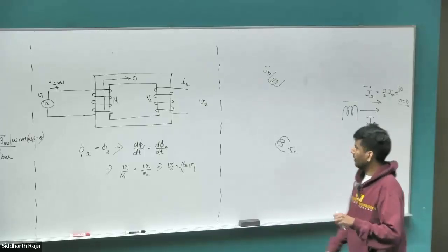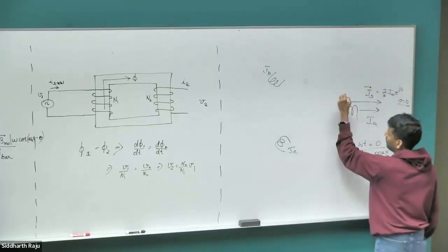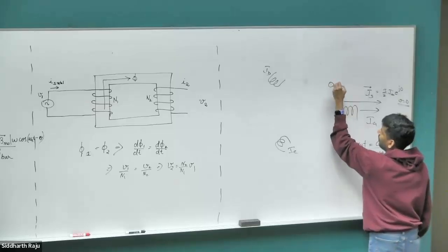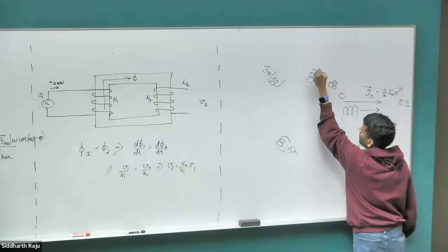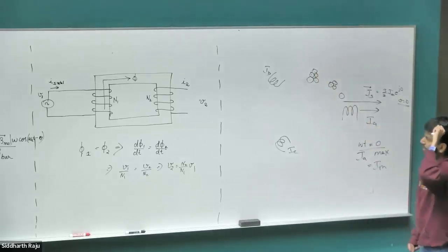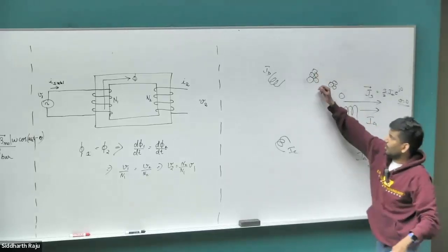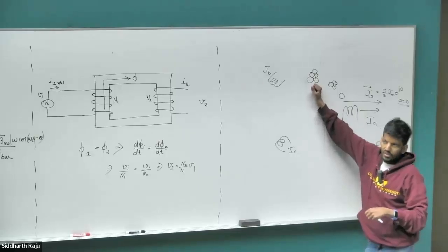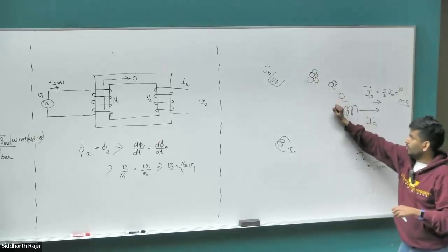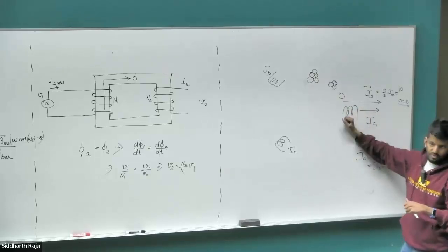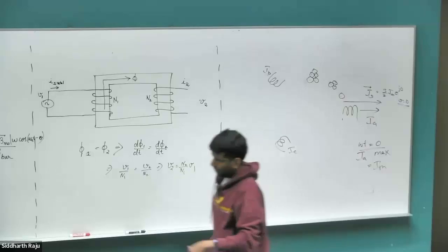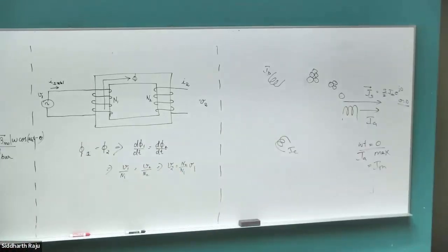90 degrees? 90 degrees. So when we have our conductor distribution, if you remember, we had one coil here, 3 coils here, and the maximum number of coils was at this point. So the Ni product is actually maxima here. And the Ni product is gradually reducing, with the lowest value being along where the magnetic axis of the coil is actually present. So go back to our own drawing in this portion.